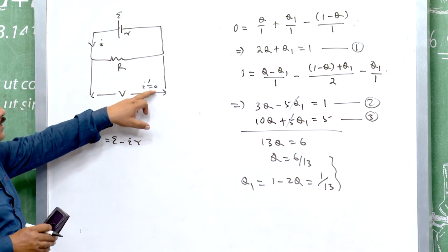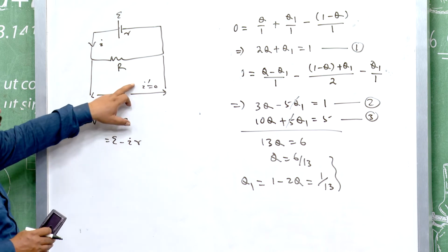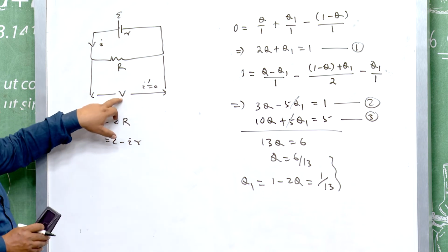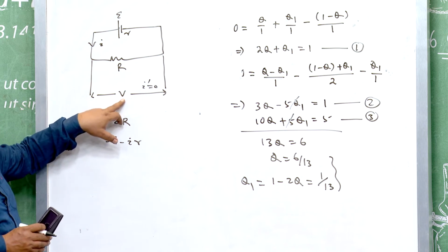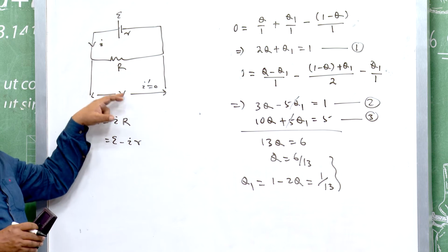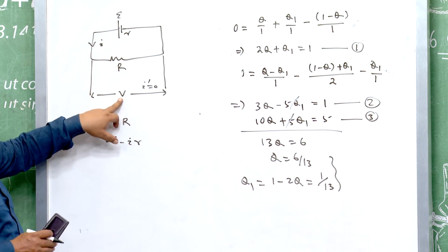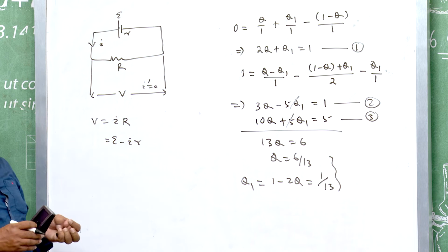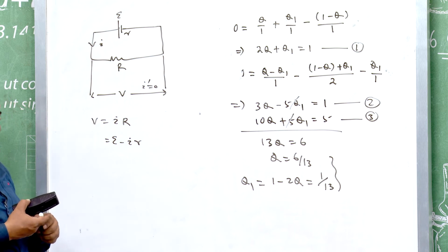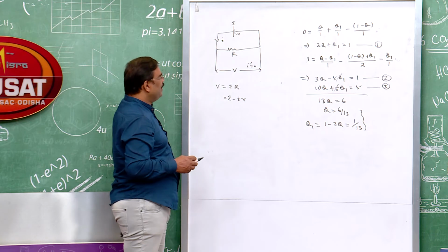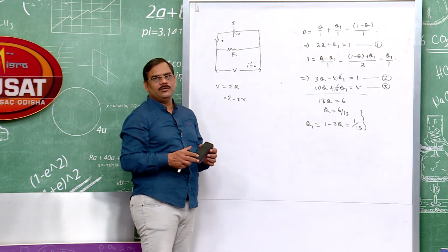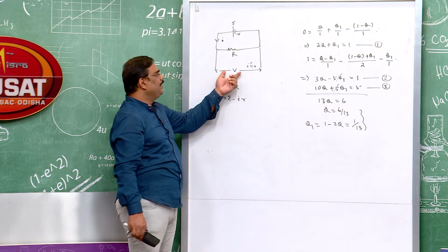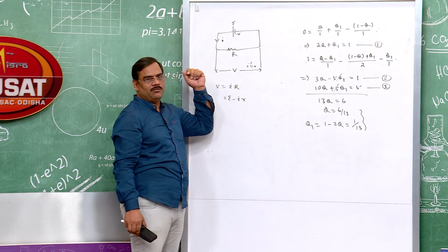But to get I dash equal to 0, we have to make the resistance of this voltmeter very high, or we can say infinite resistance, which is not within our control. We cannot make the resistance of a voltmeter infinity. This is a very absurd thing. Therefore, it is impossible to measure the exact potential between 2 points in a network by using a voltmeter.